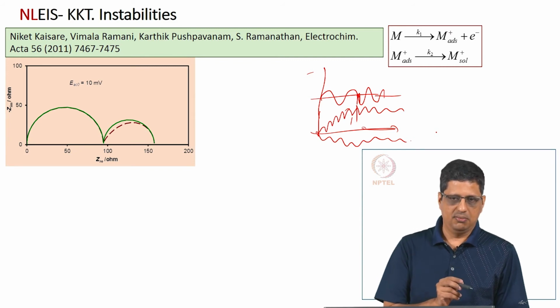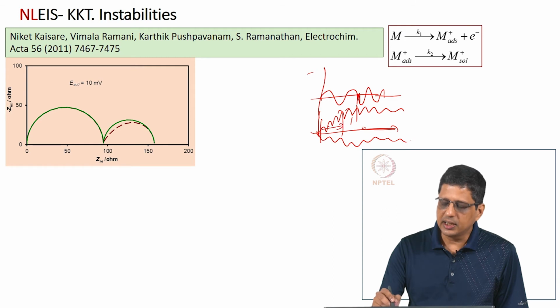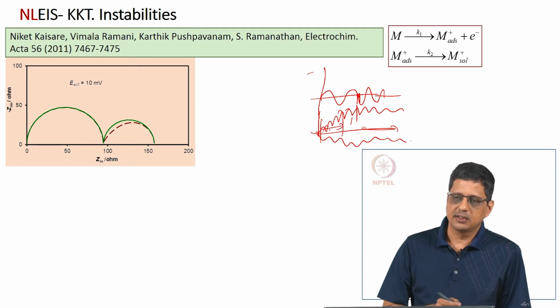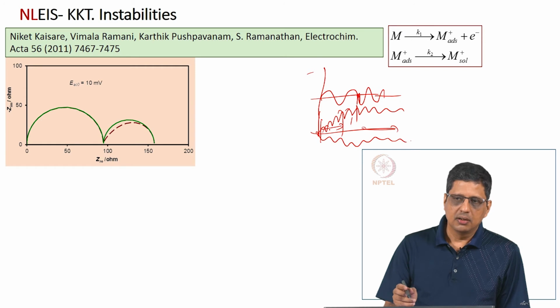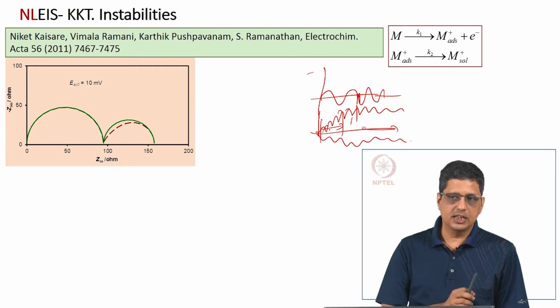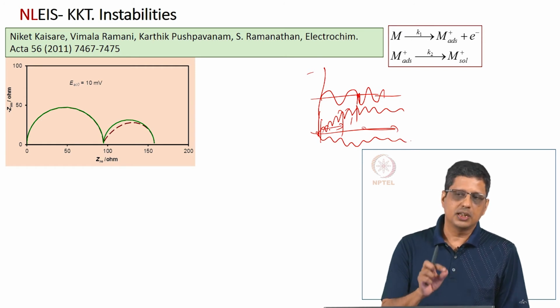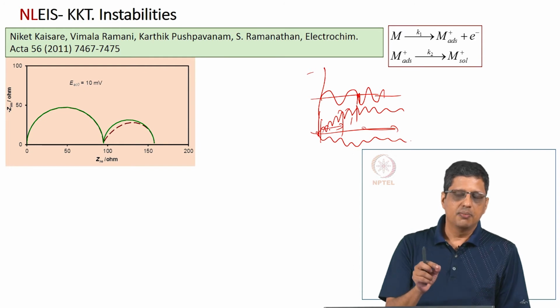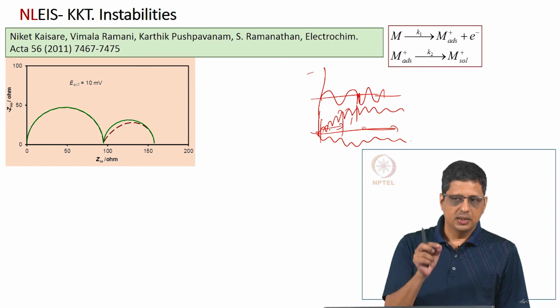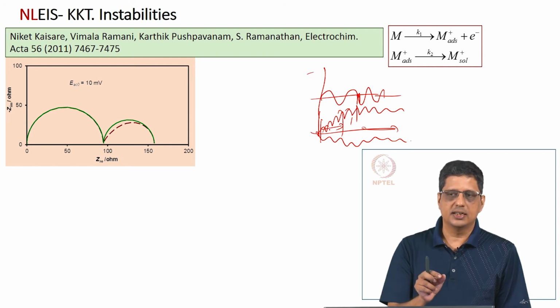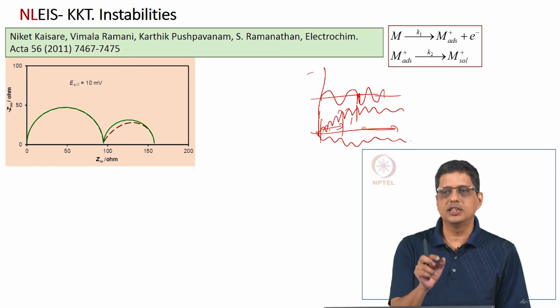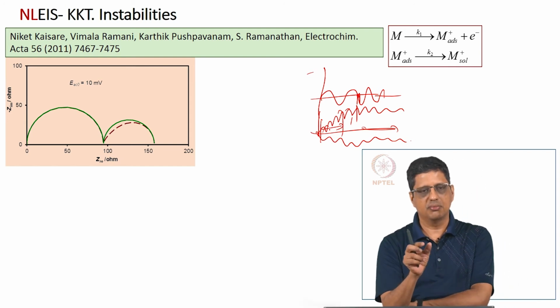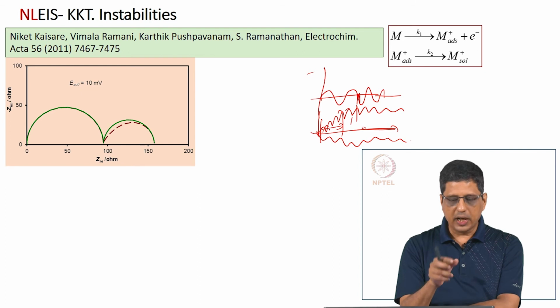However, if you record the data here and call that impedance, then normally one would not say that the system is unstable, the system is stable, because when I apply a perturbation it responds, when I stop the perturbation it goes back to the original condition, that is all right. But there is one more point, that is when you record the data, that should come from steady periodic result. If you take the data before the system achieves steady periodic condition, then what happens is this.